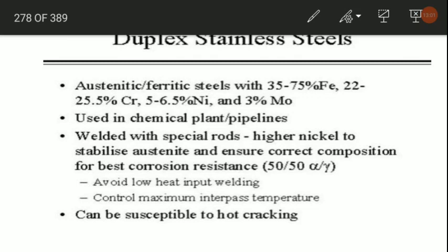in use today. Dozens of alloy variants make welding stainless steel more complicated than welding traditional carbon steel. However, while stainless alloys were once considered a major challenge to weld, today they are described as different as opposed to difficult among most welders. Stainless steels are high alloy steels containing a minimum of 10.5% chromium. Also, they are usually alloyed with other elements to improve heat resistance, mechanical properties, and fabricating characteristics as well. And I have already discussed with you the types: ferritic, martensitic, precipitation hardening, duplex and austenitic.